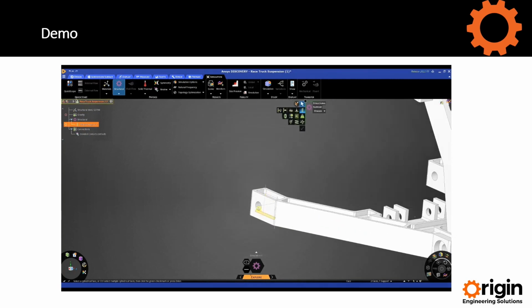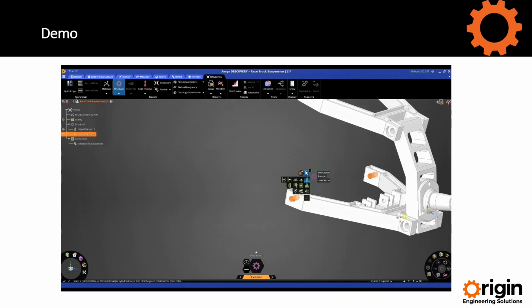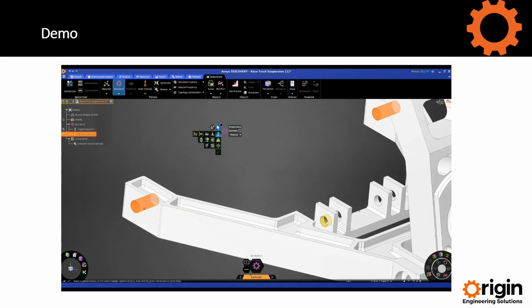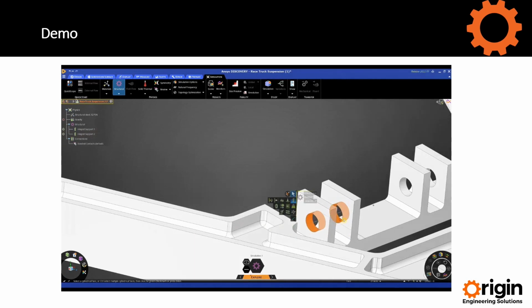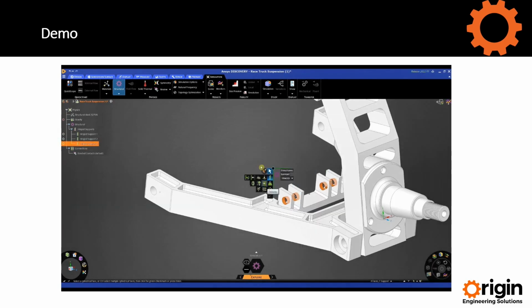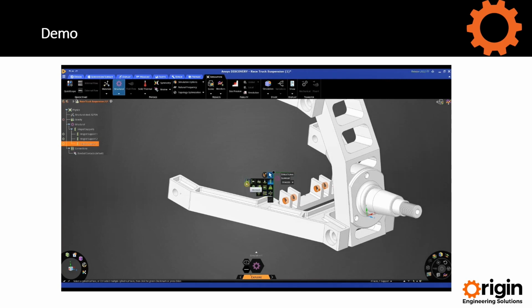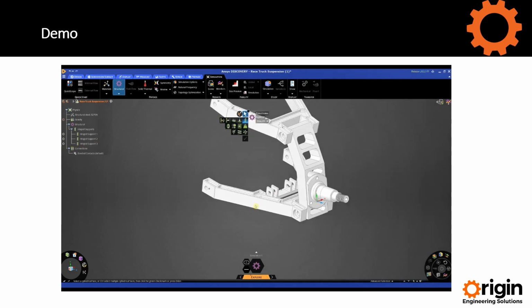So I'm going to apply a few more supports. Let's do one for here and here. And let's do the final one through these 4 pieces down below here. So we've applied our supports as such. And you'll notice that I've applied these coaxially, so obviously we couldn't apply them all together, only the ones sharing an axis can be applied as hinge supports.